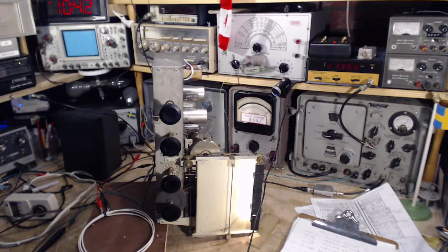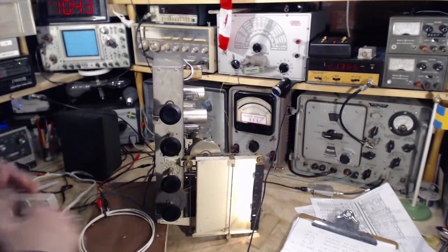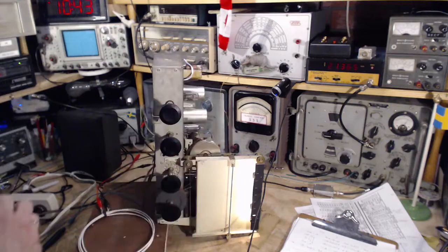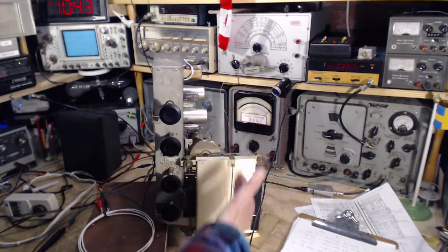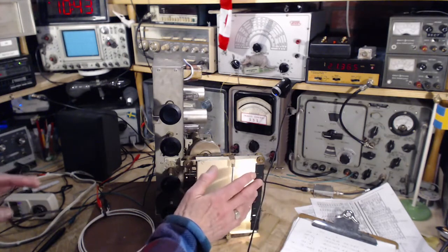Okay, I spent a little bit of time thinking about this whole situation, the journey I've been on with this radio, and what I should do next. So I think the next thing I should do is do the entire alignment procedure over again, following exactly the instructions, using a signal generator, doing everything exactly as instructed. And I'm not going to stumble over this capacitor, which I did last time around. And that's probably why when I got done and then compared the pointer with the actual dial, when I put it back in the cabinet, it was out.